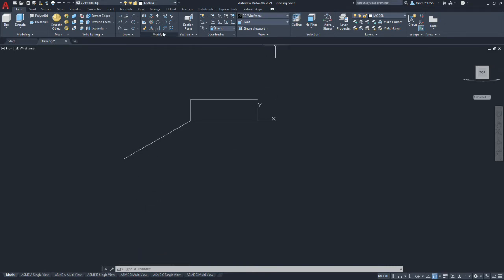We are going to offset that line by the thickness of the tab, which is 1.5. And that gives us the opposite side of the tab. What this allows us to do is descriptive geometry to project back to where this angle intersects. We don't have a dimension for that. Okay, once we've extended that, we can trim off the corner and delete this vertical line.